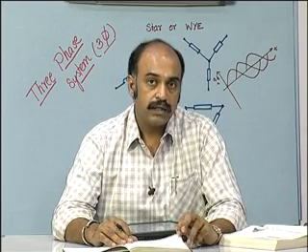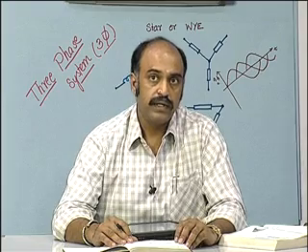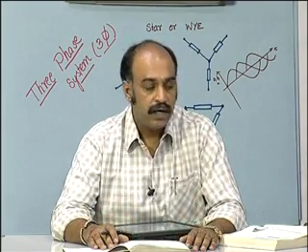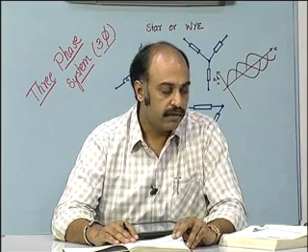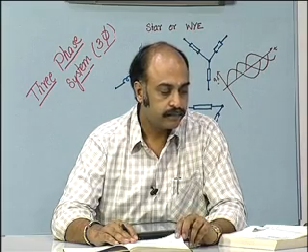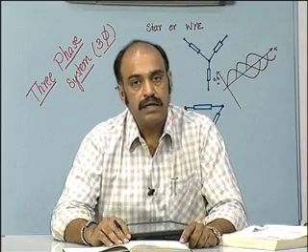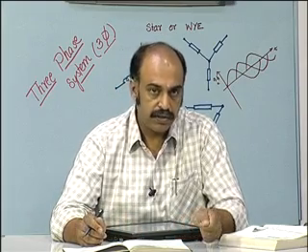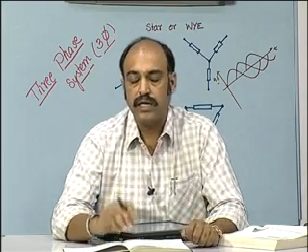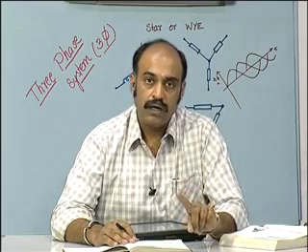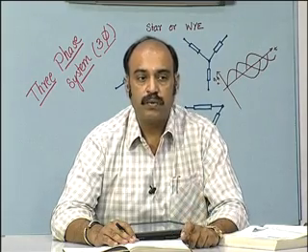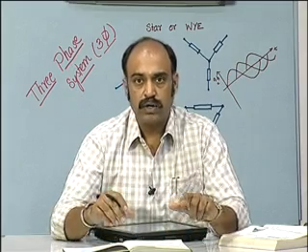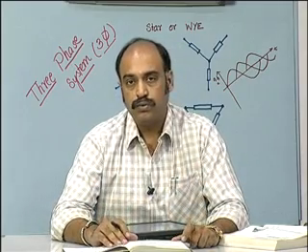In case the power factor is very low, in case it is less than 0.5, one of the watt meters can show a negative value, in which case, if it is a single direction watt meter, we must reverse the switch such that you could see the negative direction power flow, or you use a center zero watt meter, in which case you take the negative value, convert it into an absolute value, then add up the two powers.